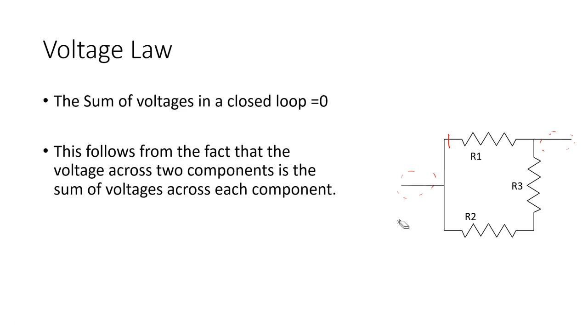So what we're going to do now is look at what it means to sum the voltages across the loop. Let's pretend that we have a voltmeter, and we could measure the voltages across each one of these points. I start off by placing one probe of my meter here, and I measure the voltage from this point to this point, and let's call that VR1. If I place my probes between these 2 points, I will just get the voltage across this resistor.